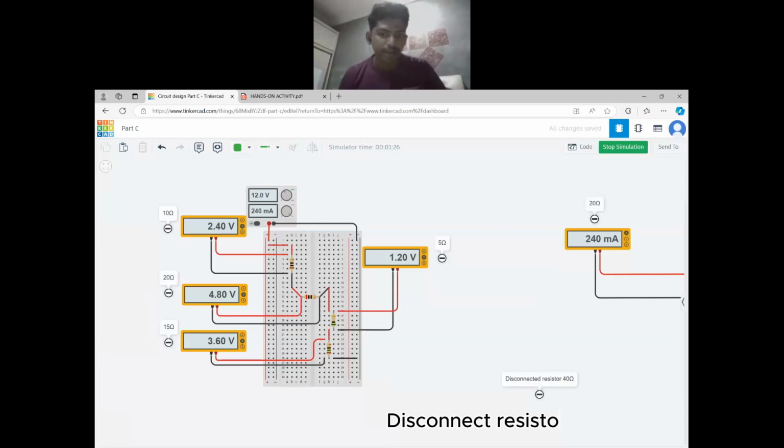As you can see, we have now disconnected the 40 ohm resistor, which is parallel to the 20 ohm resistor. In this scenario, the current can still pass through because in parallel we have two-way options. If one option is blocked, the current can pass through the other resistor or the other path. That's why we have current through the other resistors.